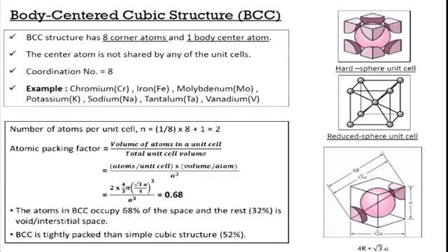So, it is A cube as the volume of the unit cell, and from geometry, in the most compact condition the volume per atom is 4/3 pi times the cube of root 3 A by 4, since this distance is root 3 A. If you calculate, you will see that this ratio comes out to be 0.68.